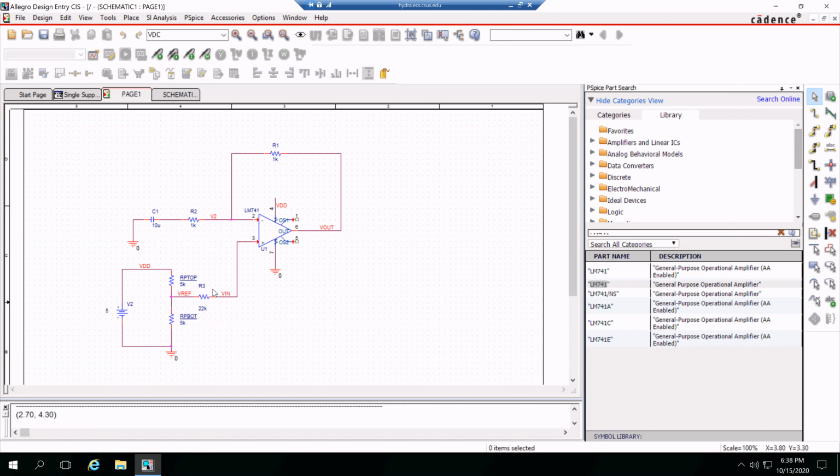So for a small signal seen looking into this, keep in mind, small signal power supplies are constant, right? So they look like a ground, just like here. So really, from a small signal perspective, it's RP top in parallel with RP bottom. So the question on number 4 for your hand calculations is, at what wiper position does the maximum impedance occur? And at what wiper position does the minimum impedance occur? I like to think of this in terms of boundary conditions. There's a couple different places this wiper could go in terms of extremes. So right now we've got it in the middle.